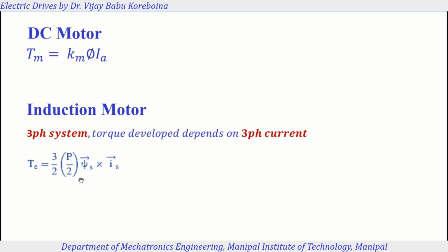So we need to understand the resultant vector of the current and the resultant vector of the flux, so that we can control it like a DC motor. Why do we need this analysis? Because three-phase analysis is not so easy. So we'll replicate the induction motor system as a two-phase system, similar to DC motor control. That is what vector control means.